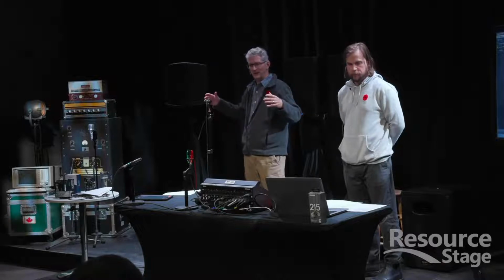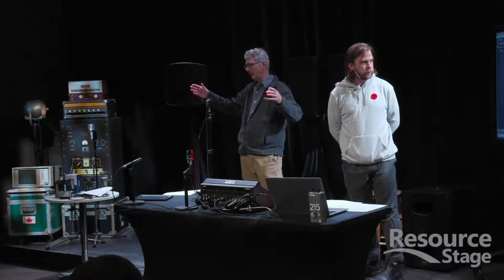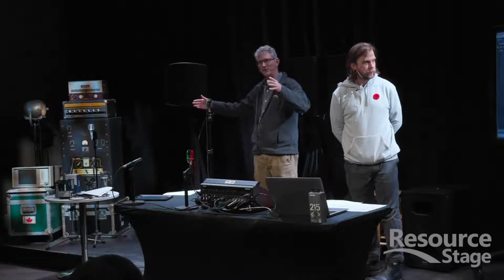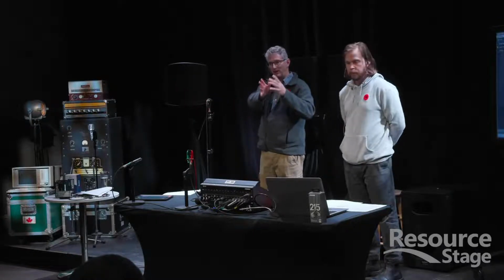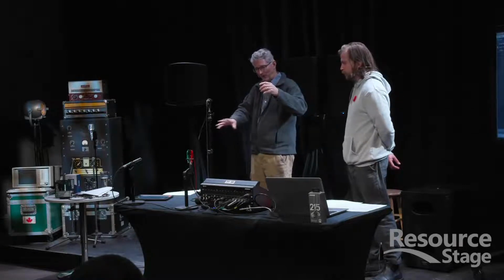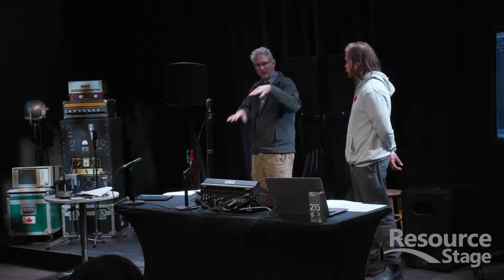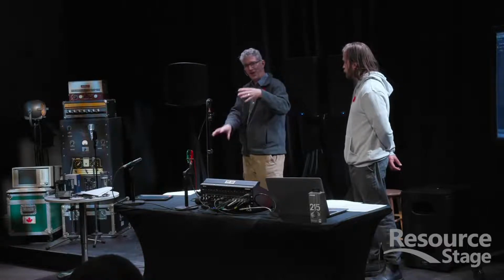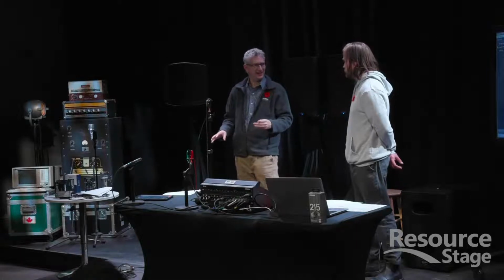If it's in a delay setting where you've got a main speaker here, and then halfway back in the room you've got another loudspeaker, and you use the subcardioid loudspeaker here, then you're cutting down on the low frequency that might be hitting the people sitting on the stage side of that speaker.